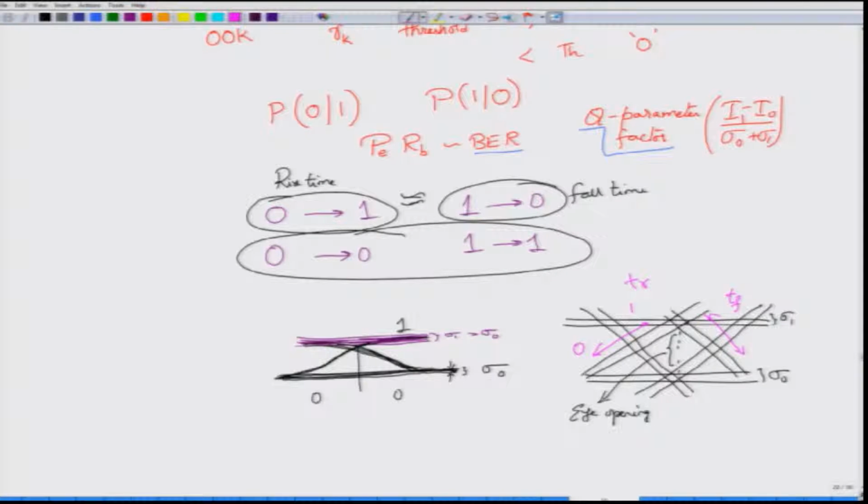If there are any other imperfections, for example, if there is a transition from 0 to 1, but because of a low pass nature, or a certain capacitive element in the amplifier, you might actually see an overshoot. And you might also see an undershoot. So, all these effects are captured by the eye diagram. The best time to sample is right in the middle when the eye is maximum. So, this is the best time to sample. Why? Because you get the largest margin over here.